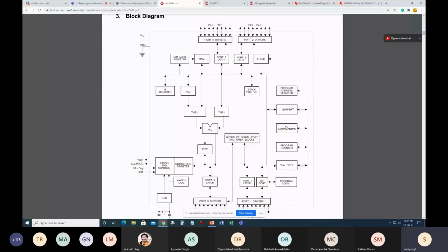Because all digital circuits are analog in nature. If you connect lots of inputs of other logic gates to the output of one logic gate, due to loading the input impedance reduces if you connect multiple gates in parallel. And now the reduced impedance is connected to the output of the first gate. If you do that, then the first gate actually cannot supply adequate current because it also has a finite output impedance. So you have to match the impedances for best performance. So in digital electronics also, impedance matching is necessary.